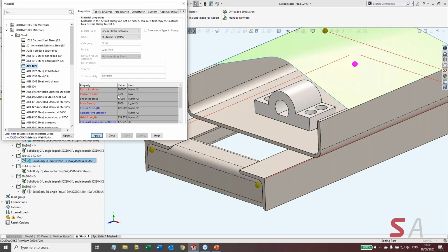But the behavior, the flexing I'm going to get, the stresses, the deformations, if you run the 2 identical studies with these 2 materials in it, your behavior is going to be the same. Your plot's going to be just about the same. This is very slightly less flexible. Let's go down to plain carbon steel. All right, plain carbon steel, 210,000, 0.28. Yield strength 220. It's less strong than either of them. So what that means is that they all behave about the same, but the yield strength is different. So if I exceed yield in my study, if let's say I would exceed yield in all 3 of them, you know that your stress result in that range isn't real accurate above yield, but you know that if you simply made a custom material and increased the yield strength to accommodate that, it would be a good result.